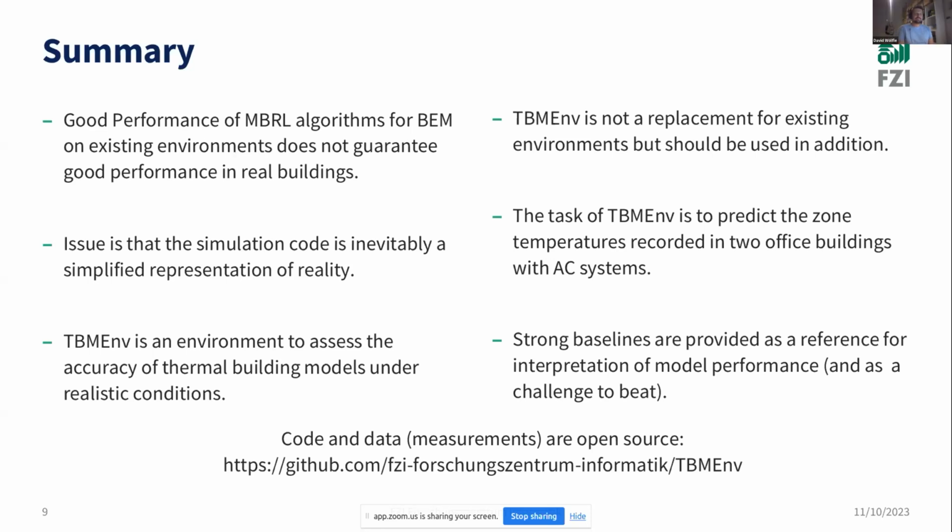This actually ties in with the previous presentation a little bit as well. So there are 2 prediction tasks you can think of being useful from a model. One is, given, say, the energy inputs or the control actions, the actuator positions, predict the evolution of the temperature profile. But the other one is, given the evolution of the temperature profile, invert the model to predict what the energy consumption would have been. So I guess I just want to ask, is that on your radar, the mapping from the actions that we take to the important output, the energy or emissions or cost or whatever it is, as an important prediction task?